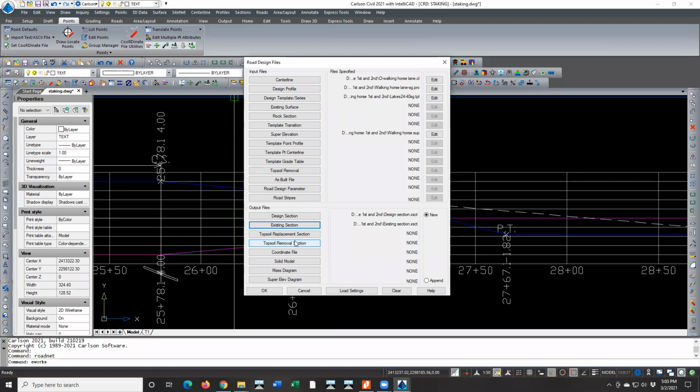Part of how that needs to happen too is that the subgrade goes out until it hits something. Usually it's that top surface. So wherever that top surface needs to be, say in a fill area, the subgrade usually would run out until it daylights through that fill slope.